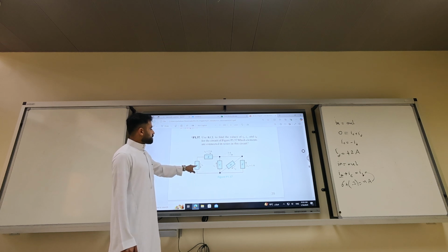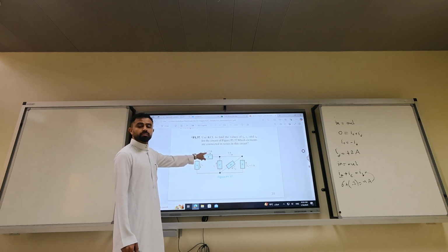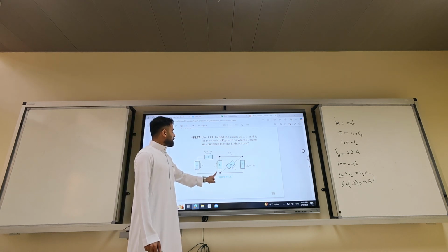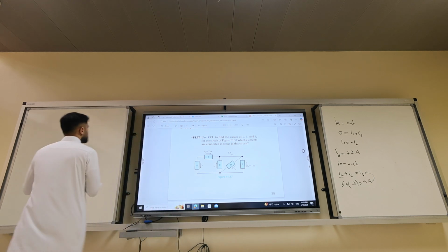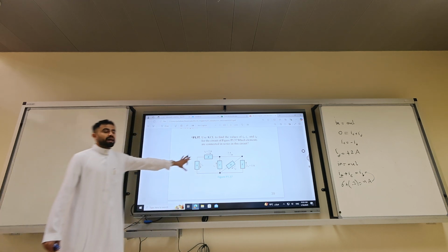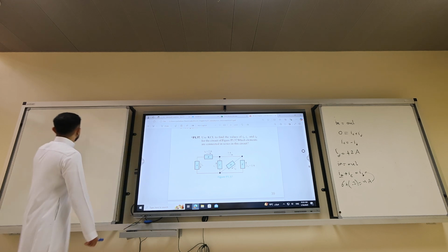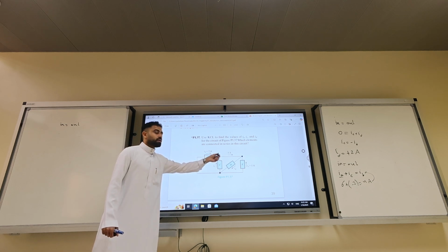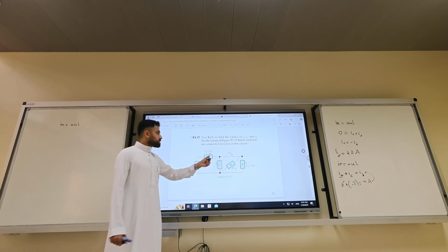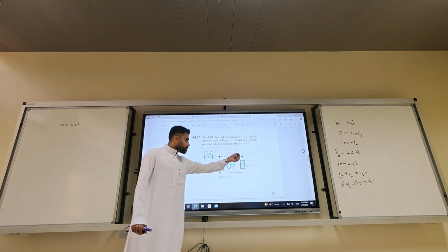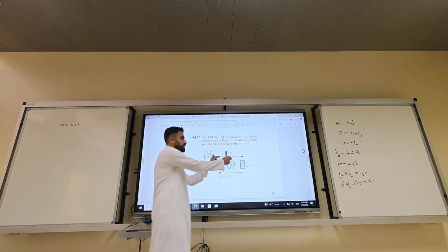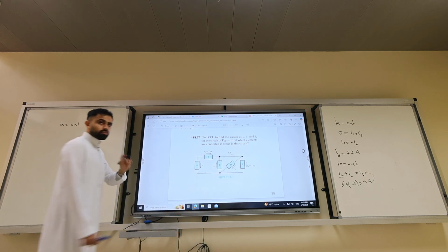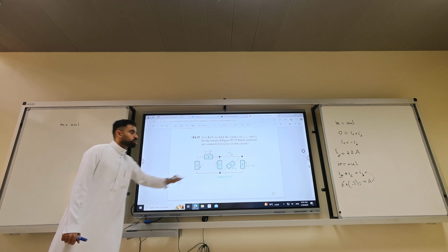We have IA equal to -2. Okay, so now we found IA. What is IC? Current in equals current out. So we finished IA, IA is easy. Let's solve IC. In equals out. What is in? This node. Now again, don't confuse yourself. This node, we're spacing it, but it will have the summation of the current flowing inside it. Now, this is a tricky problem. That's why I wanted to show it to you.